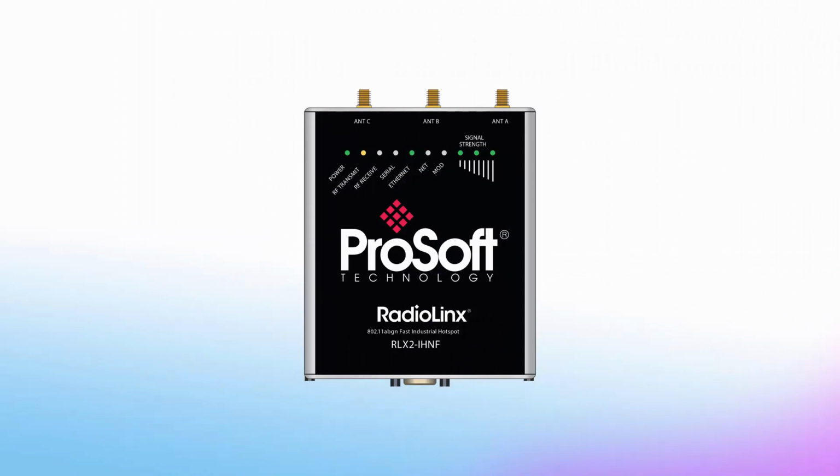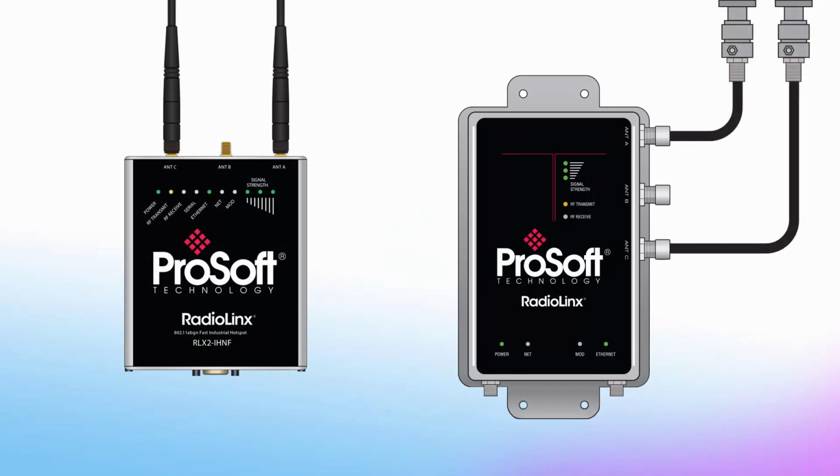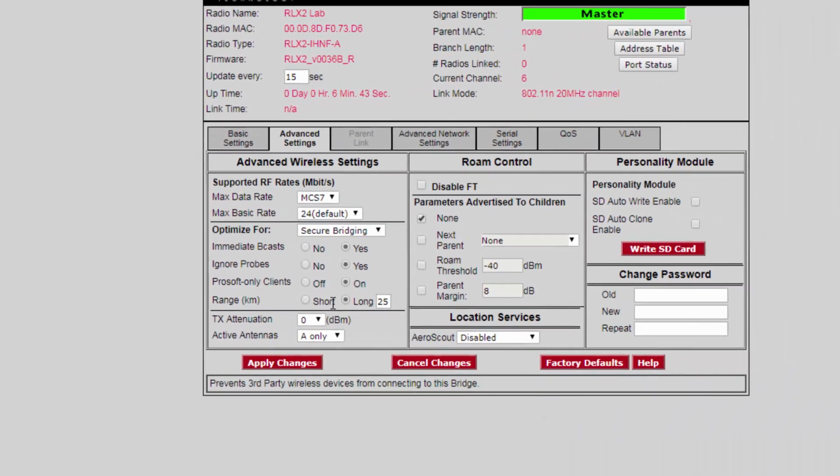If you're using a radio model with multiple ports, you should connect the antenna to port A if you're only using one antenna. If you're using 2 antennas and you have a radio with 3 ports for use with a multiple input, multiple output antenna, they should be connected to ports A and C. On the radio's web configuration page, there is the Advanced tab to see active antennas.